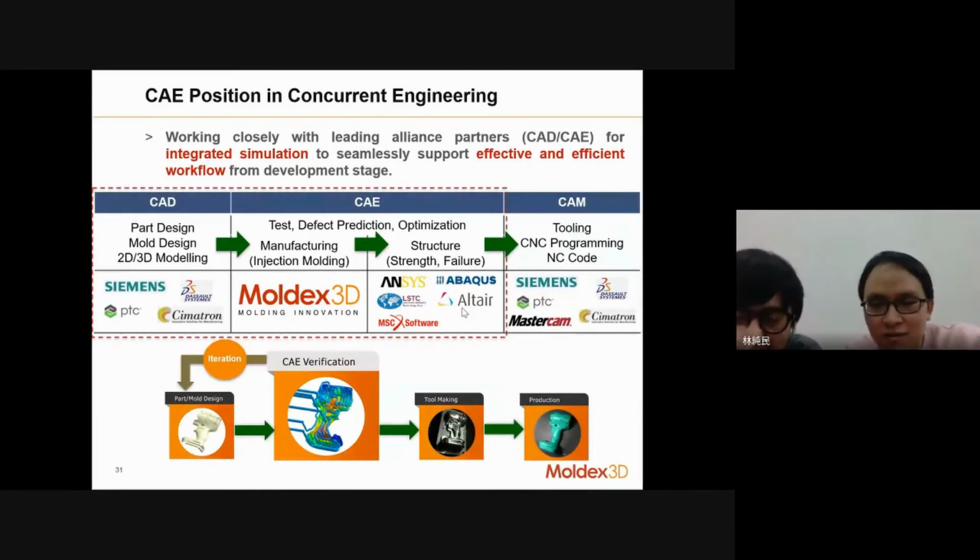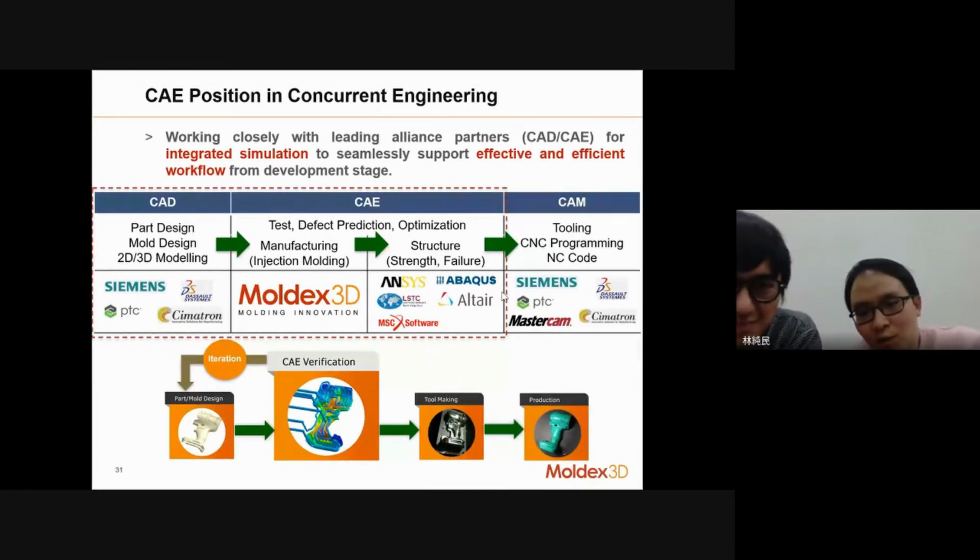The reason is that maybe you neglect, for example, the fiber orientation. You don't run the fiber orientation simulation in ANSYS. You need Moldex 3D, so you need to run the manufacturing process in CAE software. On this side is Moldex 3D, and you get the fiber orientation. Then when you do the crack test, we also consider the fiber orientation, or maybe the weld line. And when you rerun the crack test in ANSYS, you find your part actually cracks. Whether it's popular or not depends on the market.